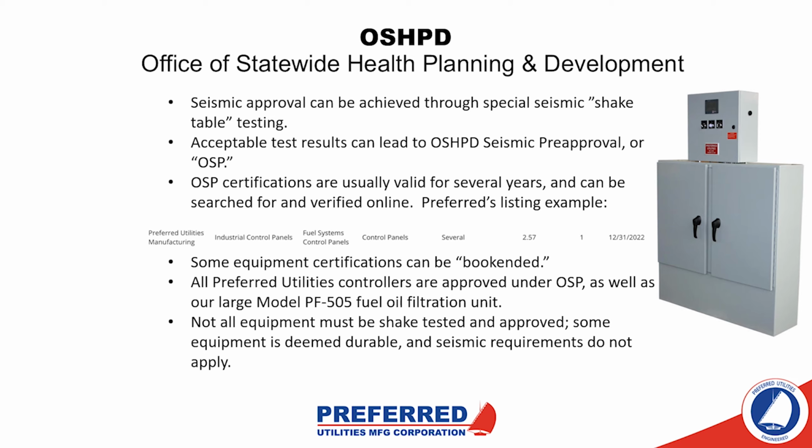So sometimes there are locations on projects where normally a piece of equipment may need to be seismically shake table tested, but if it's outside of the seismic zone, then it will not need to have the certification. So there are some exceptions to the rules, but generally there you have it as far as seismic shake table testing approval for OSHPD.